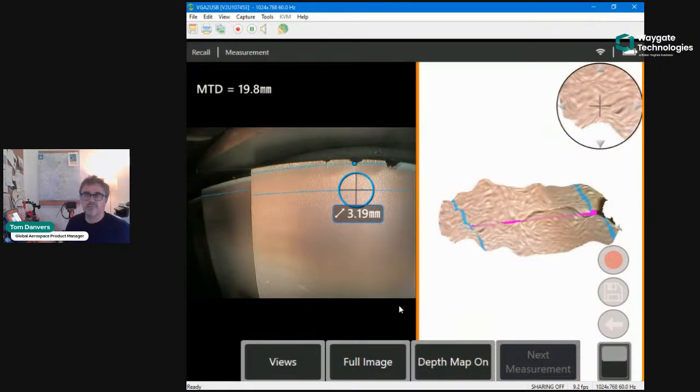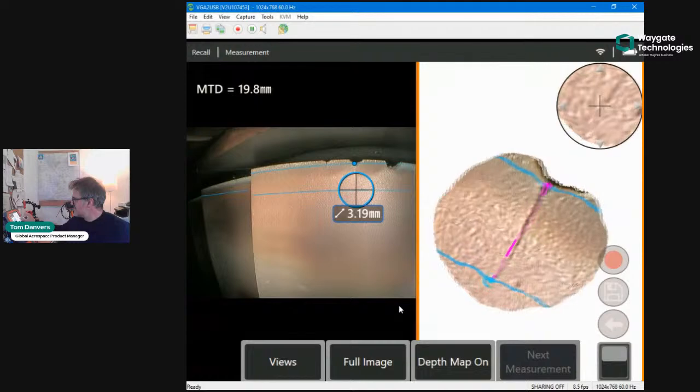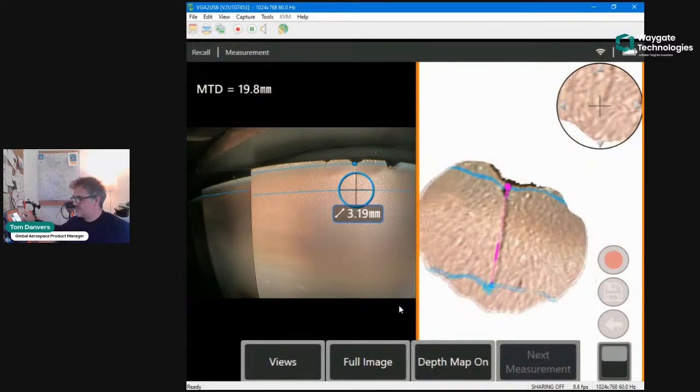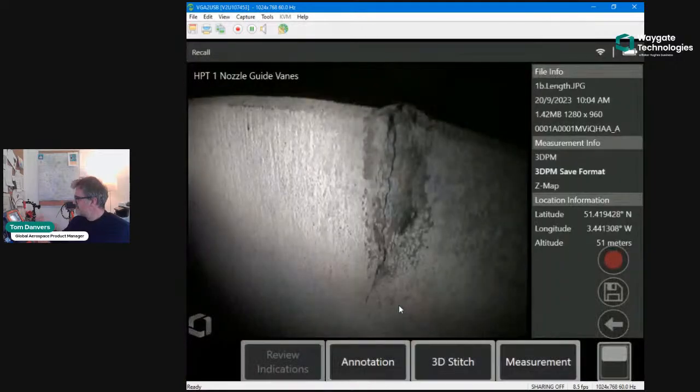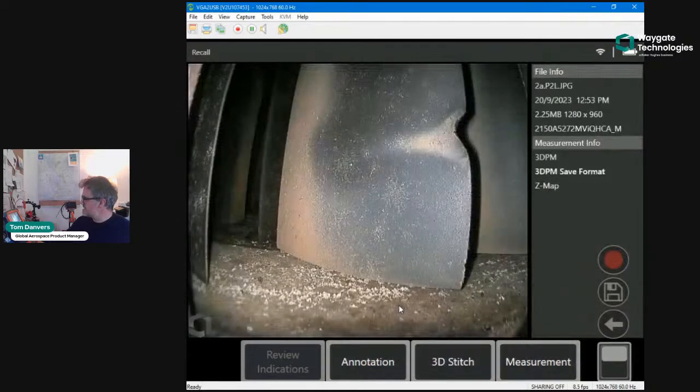And I always say this all the time, so forgive me for repeating myself: always check your point cloud. That's talking about the quality of the point cloud, but also checking that your cursors are placed in the right position. So, another crack. I won't go through this. I'm conscious of time passing very quickly, so that's really best for a point to line measurement.